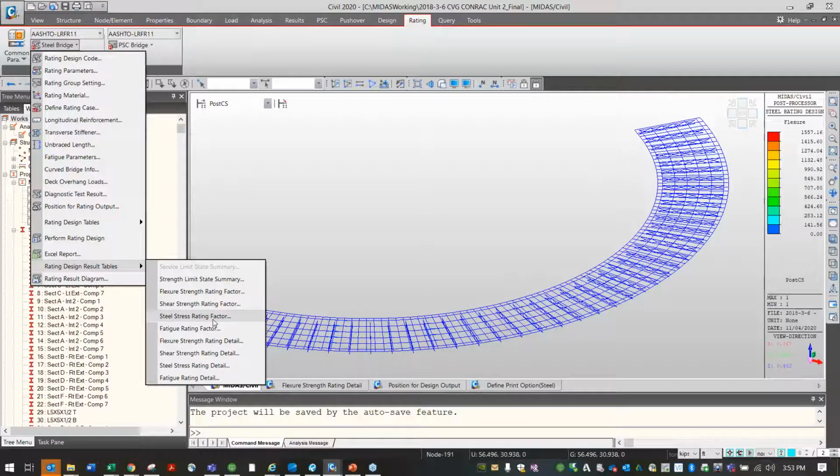And what you're really looking for, if you want to know that curvature effect, is you're going to use the steel stress, which is that fbu plus 1/3 fl compared to the overall maximum capacity stress based on lateral torsion buckling, any hybrid factors, whatever else you got. So that would fully incorporate the lateral moments that you're seeing.